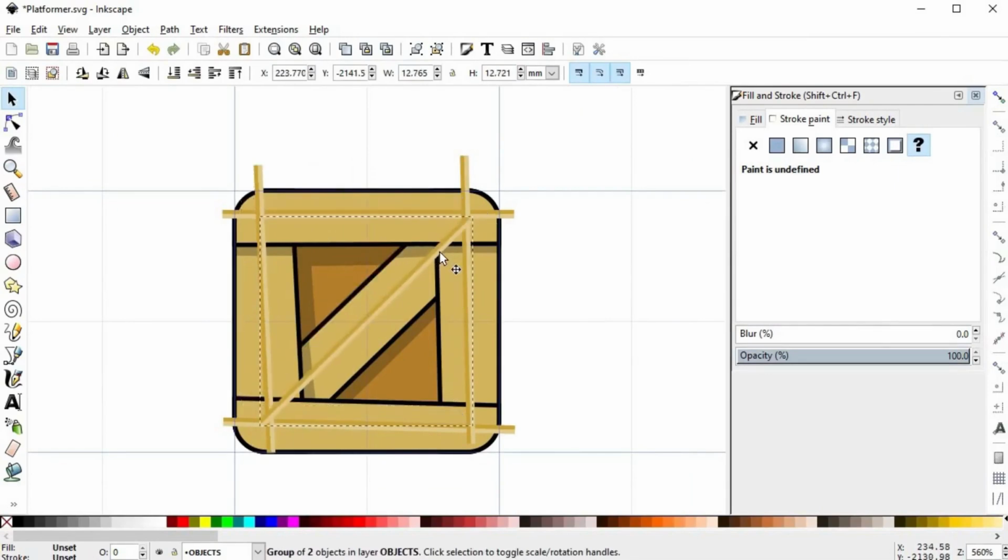Great, now it's time to remove the parts that are sticking out. We have two options, to use an intersection or to limit the visibility using clips. Previously I said that I always prefer to use intersections for simple cases, because they tend to prevent problems down the road with more complex illustrations.